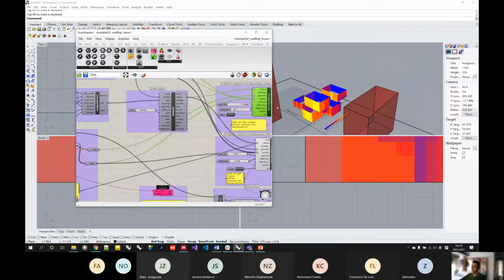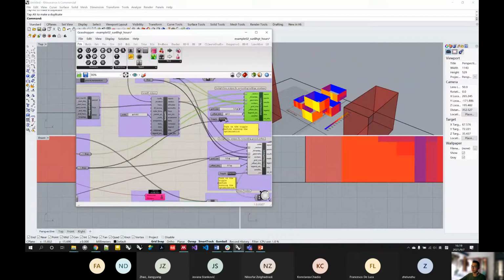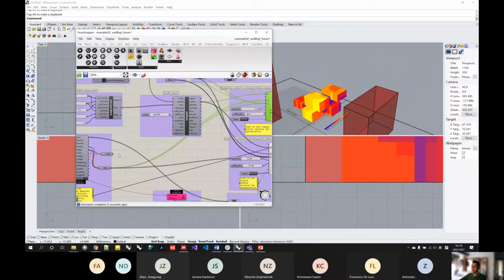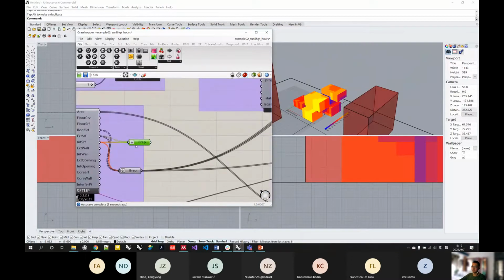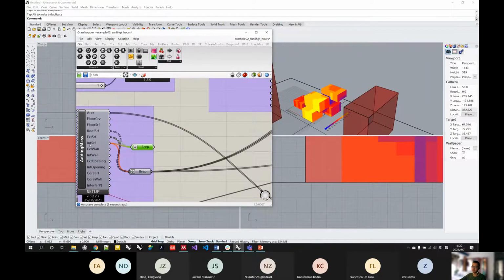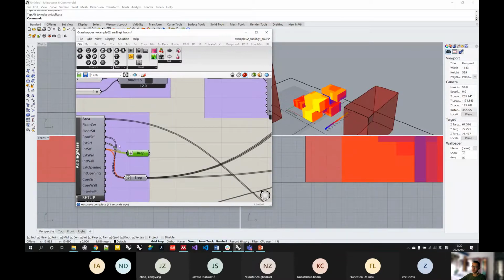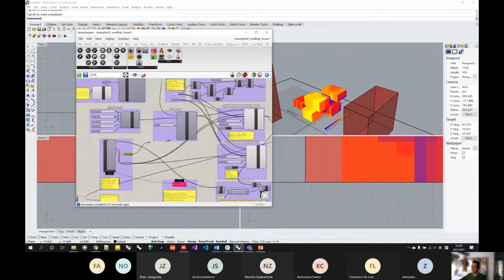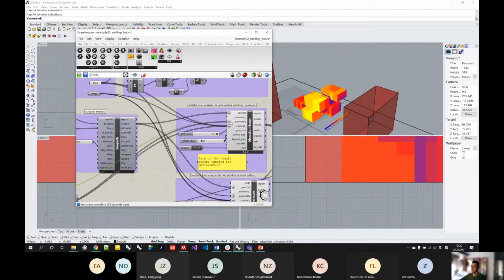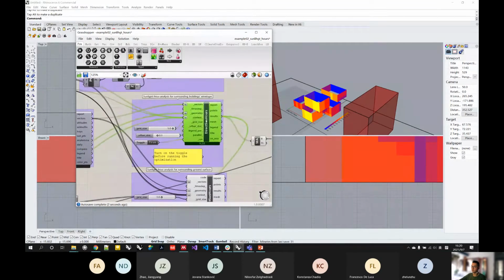So if you are still using the one that connects the roof, you can just make another BREP and connect the exterior surface and interior surface with this BREP, and do not connect the roof surface, and then connect this BREP to the geometry of this simulation component.